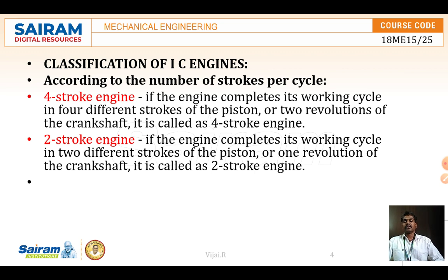After that, again, exhaust. So intake, combustion, expansion, and exhaust. We say four different operations. All four together become one cycle. So to complete one cycle, these four operations are needed. The sucking operation, that is fuel intake, is needed, fuel compression is needed, and then burning, then expansion, then the smoke created inside has to move outward. That is called exhaust. All these operations are needed.